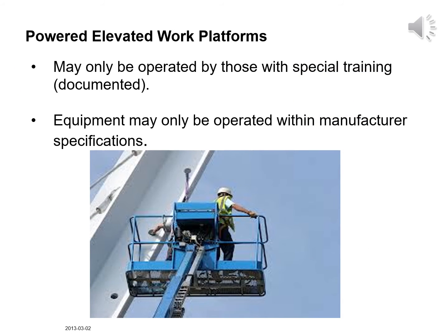The most important tip to remember before operating any powered elevated work platform is to always read and follow the manufacturer's safety and operation manual. Only trained and authorized employees should operate the equipment. A qualified instructor must make sure that every operator reads and understands the equipment's safety and operating instructions. This includes all of the warning decals and labels mounted on the machine.